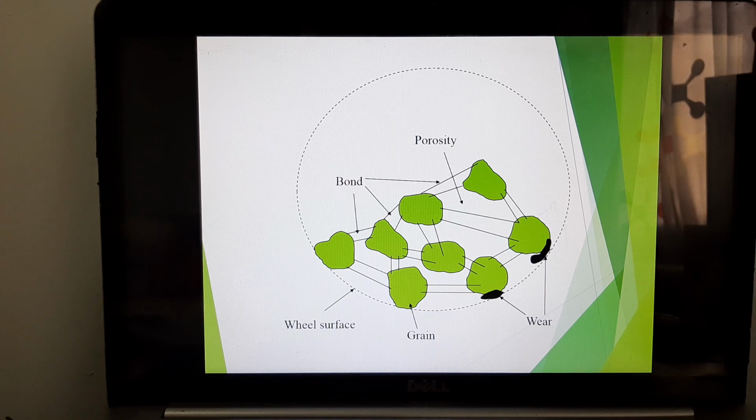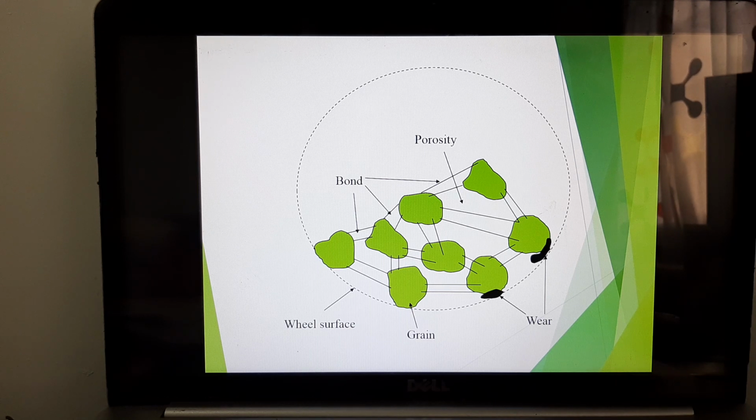Rough grinding depends on the manufacturing process you have chosen to apply. In finishing processes where the outcome of the product is not as satisfactory as expected, meaning that the surface finish of the product is still rough, you may start first with a rough grinding.